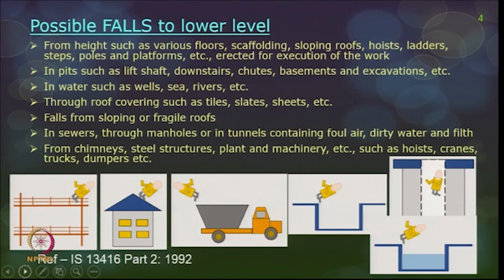In pits, okay, so falls need not always happen from a height above your ground floor to the ground floor. It can also happen from the ground floor level to what we call a basement or a pit or an open hole. So, in pits such as lift shafts or downstairs or chutes, basements and excavation, into water, maybe you slip inside a water body, so it can be a well, sea, etc. Through roof covering such as tiles, slates or sheets, and falls from sloping or fragile roofs.